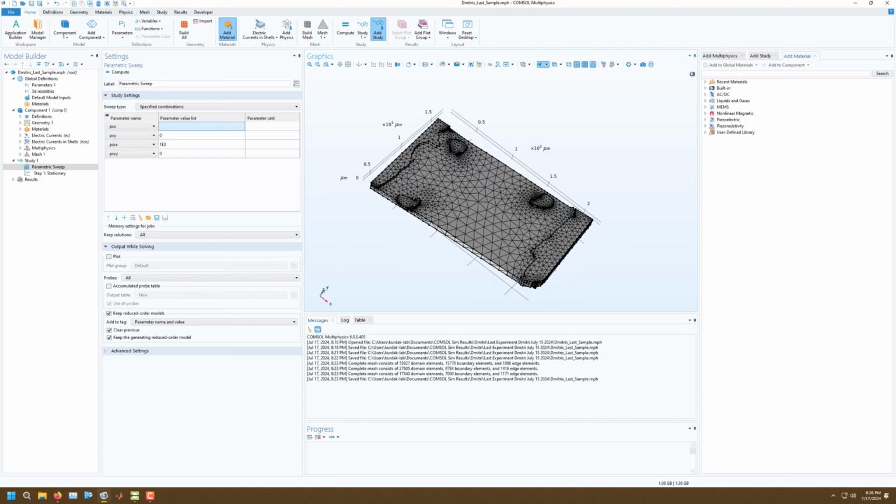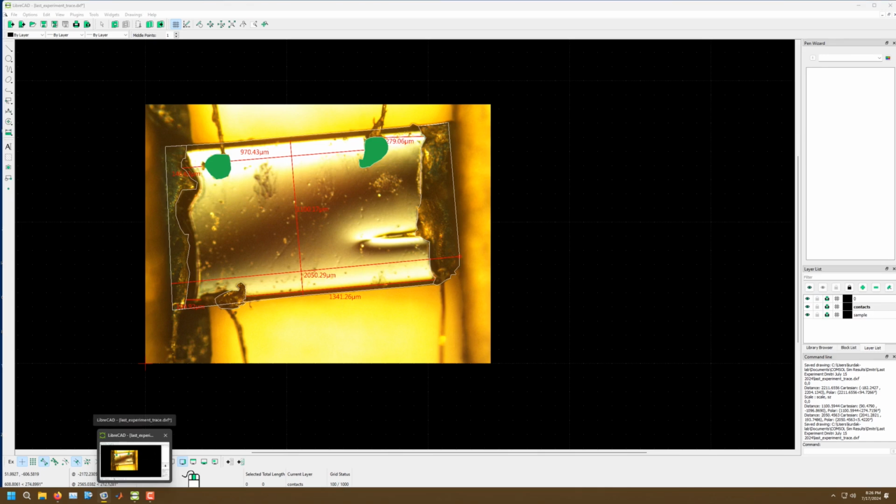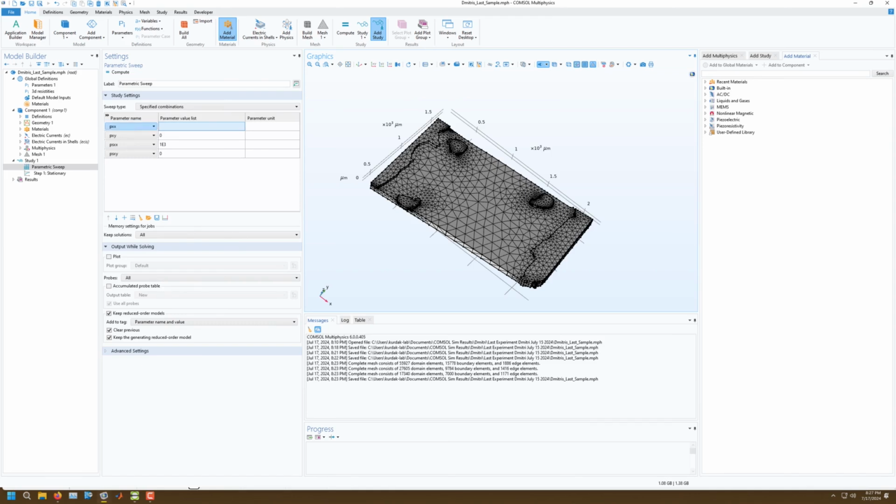I guess then I gotta multiply by the distance between them. Hold on, let's do this right. Let's do it right. So 0.43 e to the minus 6. Okay, so it comes out to about 1,000 ohms. So when the bulk resistivity is very high, the back of the envelope calculation gives a sheet resistance of about 1,000 ohms between these two. Alright? But that's just when you are very high. When you're very low, this guy will take over.